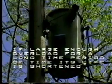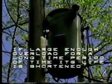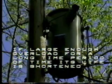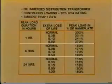If a distribution transformer is subjected to a large enough overload for a long enough period of time, its life will be shortened. Loading guidelines published by the American National Standards Institute define the allowable magnitude and duration of overloads for distribution transformers. We should point out that these guidelines are quite different than for the substation transformers.